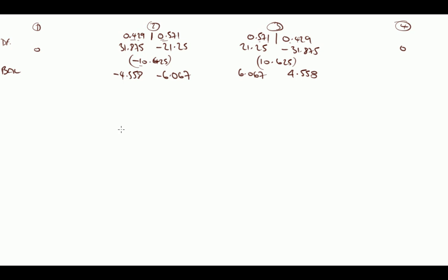Okay, so that is our distributed balancing moment, and we need to remember that we have this carryover step to do. So our carryover moments coming this way just come to nothing, because this is a pinned end, so nothing can carry over to this side.